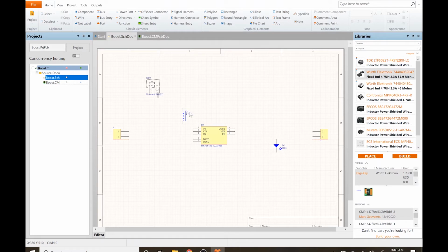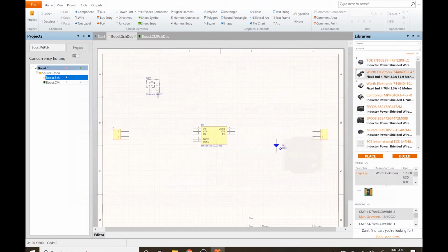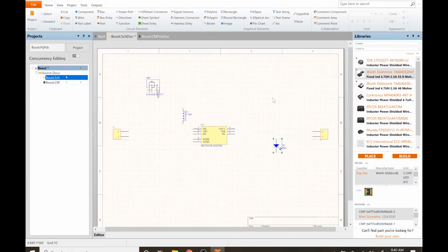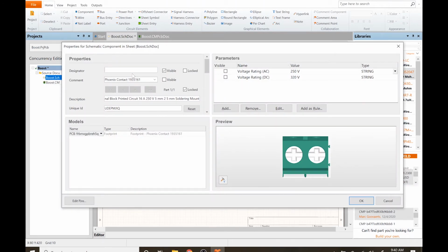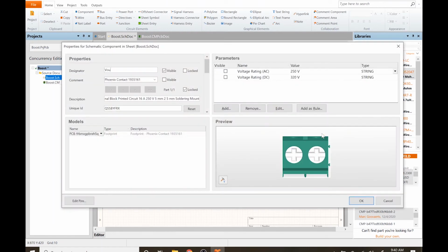And click OK. So now it tells me that it's L question mark, and that's a designator. I'll show you how to actually change this all simultaneously in another video. But for now, we can just go here and click L1 because we only have one. And so now we've got L1 and 4.7 microhenries, and this is D1. I'll change that to D1. And I definitely want to change these to VIN. And guess what? This one's going to be VOUT. Good call.